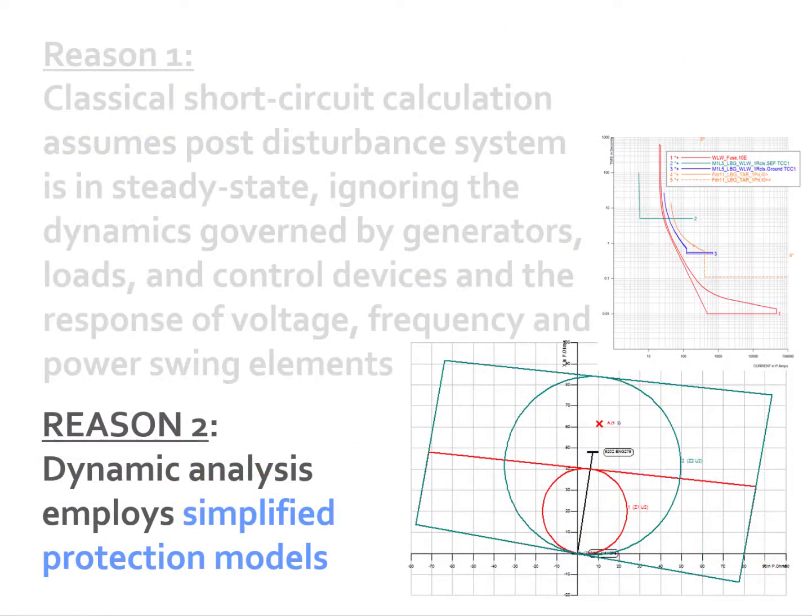The second factor contributing to the interest in IPPS environments is that transient stability programs currently either rely on theoretical protection relay operating times or employ simplified protection models using generic relay representations that simply mimic the main protection elements and assume that the supervisory elements operate. Furthermore, these simplified models require a conversion of the actual relay taps to derive the equivalent settings for the generic models.